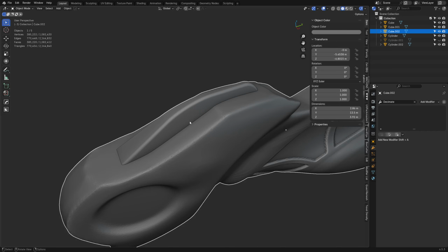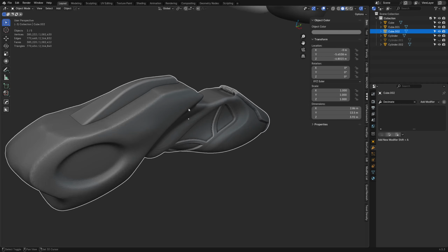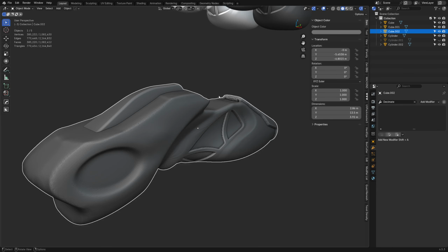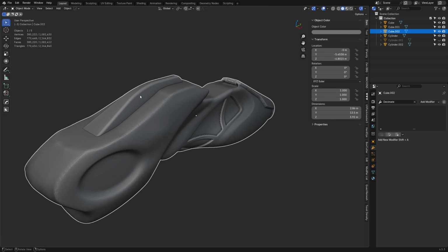So if you have the choice, if it's more cubic shapes and you know you can handle it with a Boolean n-gon workflow, do that. If you know it's easy to subdivision model, then do that. If you just want to explore things and use voxels that you know you're going to have to remesh or retopo later on, then do that. This is more exploratory, obviously, but this is a pretty clean shape.